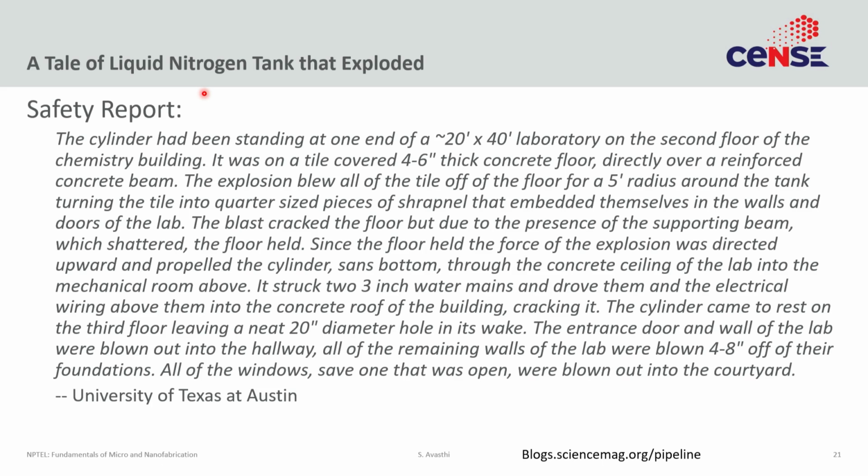So let me just read it. So what actually happened was that they had a liquid nitrogen tank. It was standing in the corner of a laboratory. All cylinders come with some safety valves, and some student or a postdoc somewhere along the way found one of the safety valves leaking. And instead of changing it, they just blocked it. So there was no safety release valve. So the system continued because it was used often. The pressure never built up to unsafe levels.